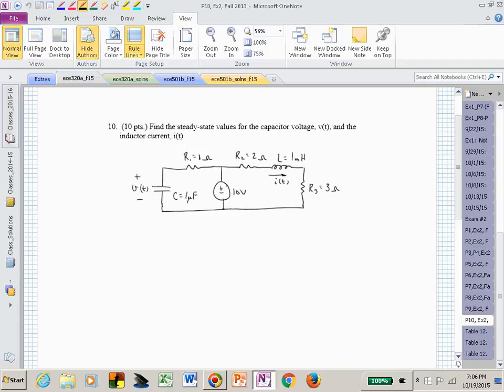But you know in electrical and computer engineering, how long is an infinity? 5 time constants. So it doesn't have to be energized for very long, and it's reached steady state conditions. And that's all you're asking. But what happens when you have DC sources applied to capacitors and inductors? This is, I think, what we started with in the topics list. The capacitor's open and the inductor's short.